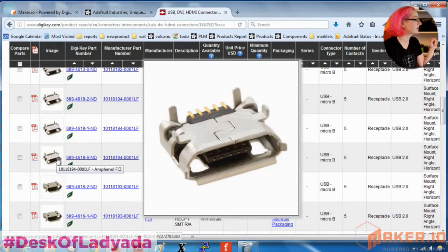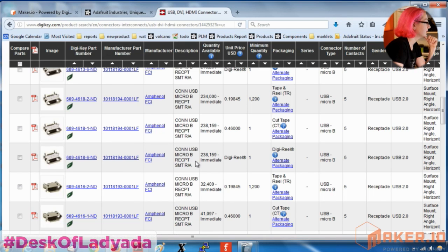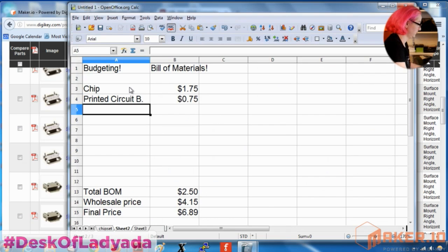And then this one you can see is 50/50 through hole SMT. There are 4 through hole legs, and the connector pads are SMT. You can actually pick and place this. Something to consider: through hole components, especially connectors, can often be less expensive, but it is a more expensive assembly step, so the cost you're paying for assembly might overwhelm the discount. This part is basically the same, so micro USB is about 20 cents.